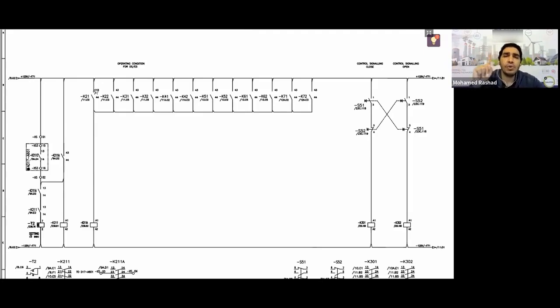This means only one component is running at a time. It means only one component is active at that moment. Then the situation evolved so that when you give a command to close or open any component, just because you gave it a close or open command, you cannot give a close or open command to any disconnector or earth switch in the entire GIS building you are in.